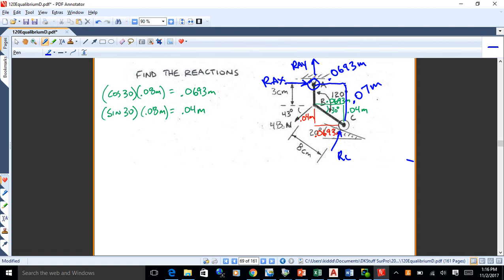And remember, X moment arms with Y forces, Y moment arms with X forces. That's how you make moments. The force and the moment arm have to have different directions, X and Y. Using X and Y dimensions and X and Y components of force ensures that everything's at right angles for those moments. That's the idea. And then counterclockwise positive and clockwise negative. That's about it.